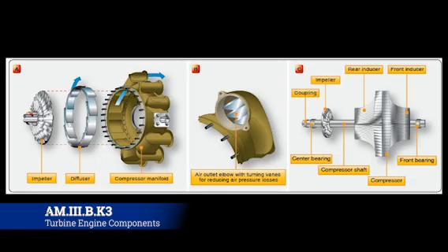The two main functional elements are the impeller and the diffuser. Although the diffuser is a separate unit and is placed inside and bolted to a manifold, the entire assembly, diffuser and manifold, is often referred to as the diffuser. For clarification, during compressor familiarization, the units are treated individually. The impeller is usually made from forged aluminum alloy, heat treated, machined, and smoothed out for minimum flow restriction and turbulence.